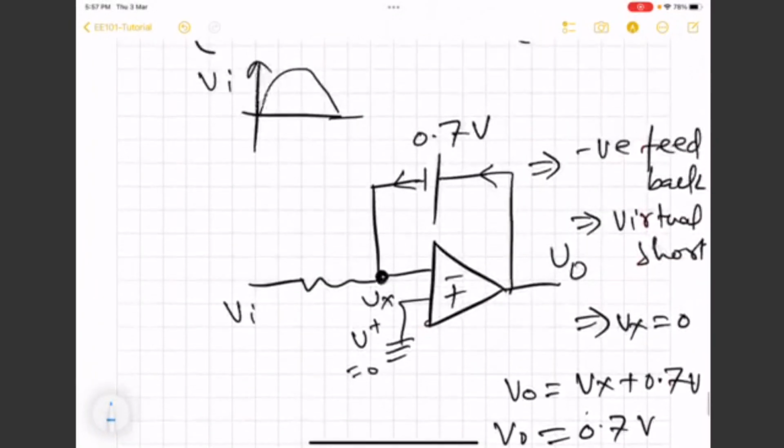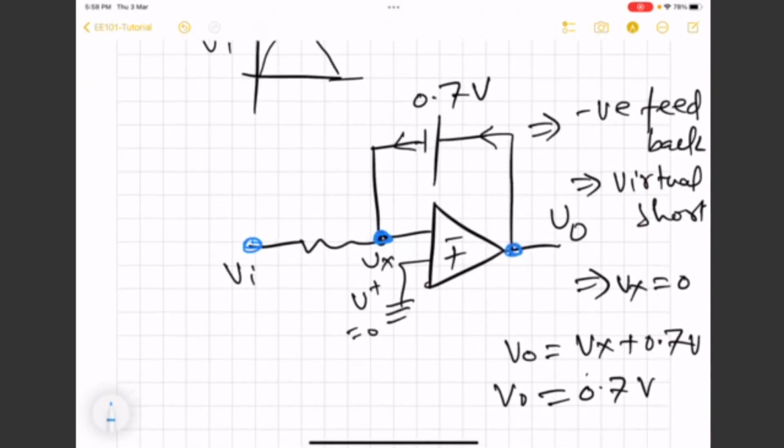And for checking whether it is going to be forward bias or reverse bias, you just try to see the polarity of this output voltage and this voltage, or rather this input. So we know that if this is negative because input is negative, this is going to be positive. So we will of course have this polarity of the voltage across diode, and diode will be forward bias.